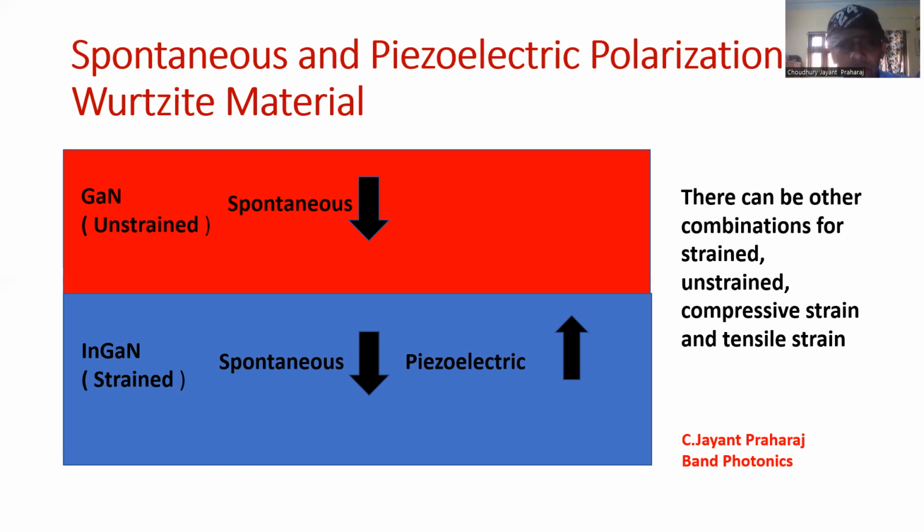But again, there are also differences in the technological complexity between the 0001 polar C axis, and then the A plane and M plane, or the non-polar axes. So we have to do the device optimizations and the growth optimizations, and we have to consider all of these in order to get the best device performance. So the polar C axis and the non-polar A plane and M plane.